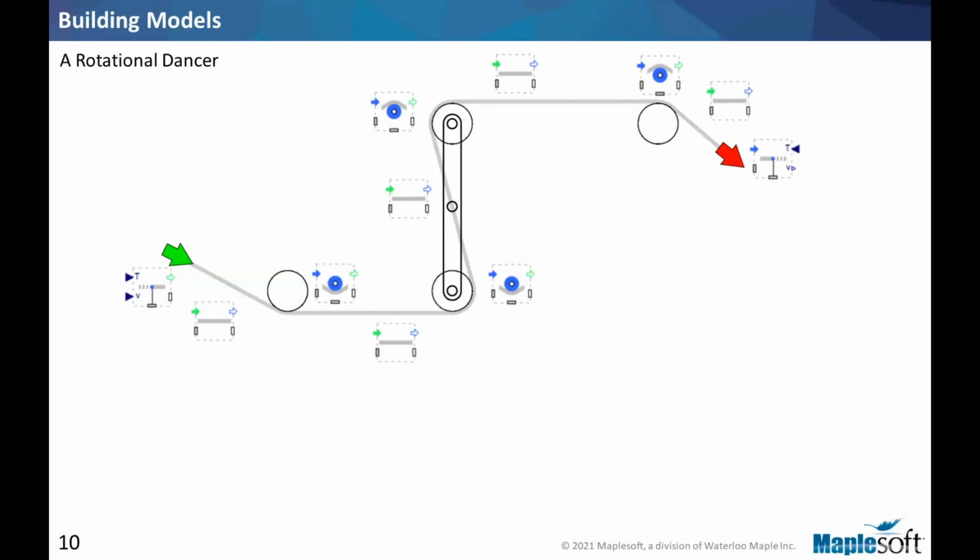Now that we have brought in our spans, we need to anchor things where they are to the ground. So we use the fixed frame and connect rollers and sources and sinks to the ground. Each component, and we will take a look once we go to the tool, has parameters. Like this fixed frame will have X, Y, and theta for defining the position and orientation. We don't have orientation changes here, so we'll put the right X and Y such that each piece in our model appears where it's supposed to be.